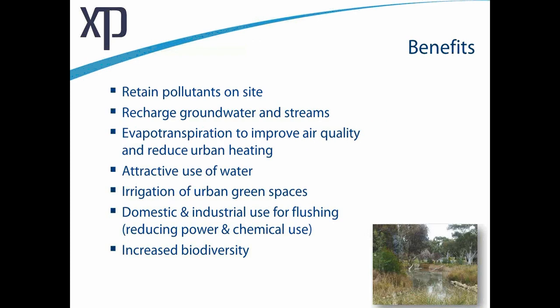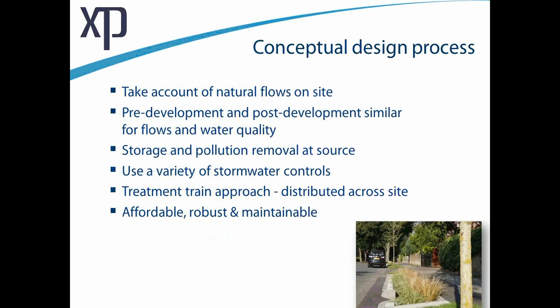Some of the benefits of WSUD, or SUDs that we're looking for, are to retain pollutants on site, to recharge groundwater and streams, evapotranspiration, which even in the cooler weather that we tend to get is important to reduce urban heating, and particularly to make attractive use of water to increase the biodiversity we're getting into our urban areas. And of course there are other benefits such as flushing to reduce power and chemical use.